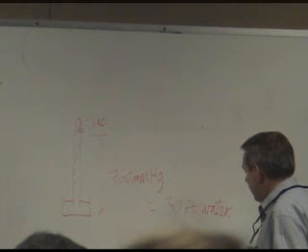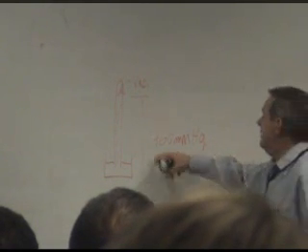And the solution to the problem is that you have to put a restriction on the end of the pipe, so that instead of just discharging the fluid straight back into the river, you put an orifice plate or a valve or something on this to create some kind of delta P, so that then you'll keep this pressure above the vacuum condition. But again, it's a very strange sort of problem, and when we first explained this to them, they thought we were crazy, but they tried it and it worked. And it's just simple